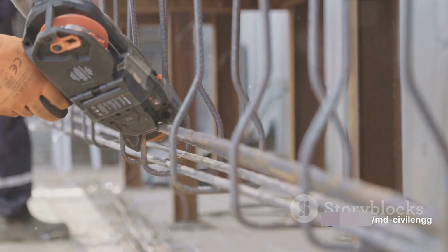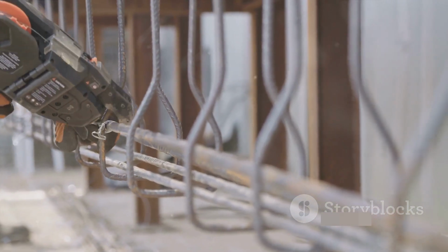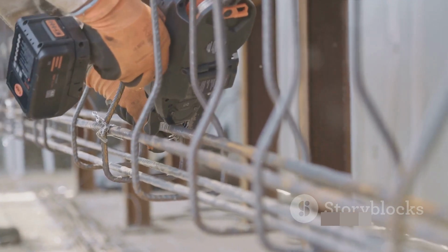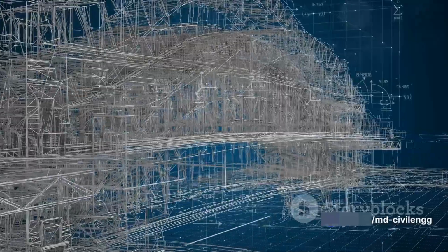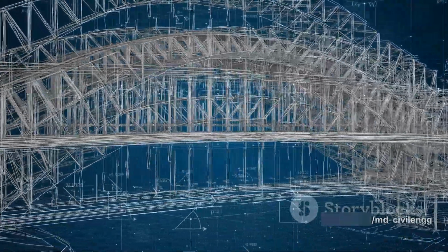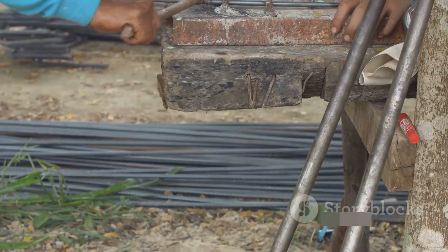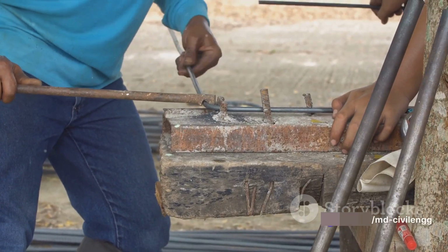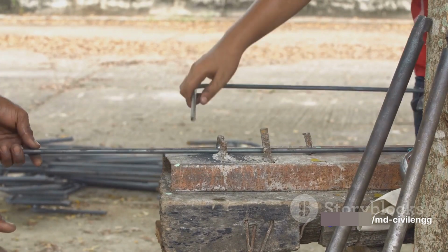This might not sound like a lot, but in the world of civil engineering, every bit of strength counts when it comes to supporting structures. So, how do we calculate this? Let's break it down. For a short column with helical reinforcement, the load carrying capacity, denoted as P, is calculated using the formula P equals 1.05 times the sum of the stress in compression steel, represented by SSC, times the area of compression steel, ASC, plus the stress in concrete, SCC, times the area of concrete, AC.